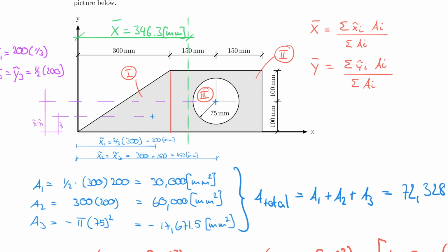And I show that I understand where that centroid location is. And by the way, something similar is true for Y bar. If we had a complete area here, then Y bar was exactly half of 200, so it needs to be less than 200, right? However, we're also removing this, so we'll see if this area has a bigger contribution than this, but it should be somewhere between the middle and this point. So we will calculate that next.